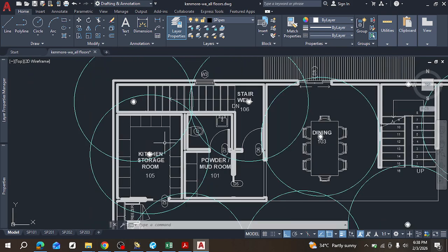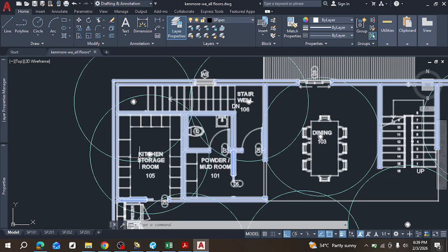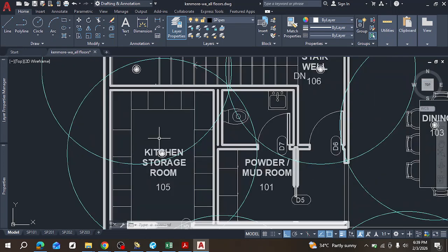And whenever you can, try to also look at the electrical plan, the HVAC plan, and other plans, because sometimes as I'm designing this, I'm designing thinking that every ceiling area here is free, but that is not always the case. By the time I get to look at the reflected ceiling plan or the ceiling plan for the electrical design, I see that there are some areas taken, because everybody wants to use the center, right? So that might be something you want to look into too. Whenever you can get access to it, please do, just to improve the efficiency.